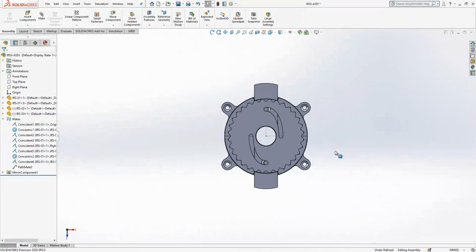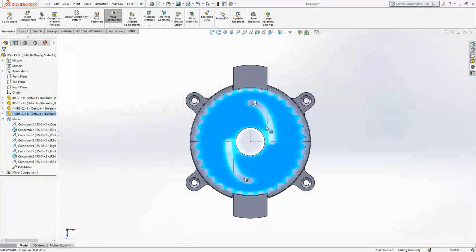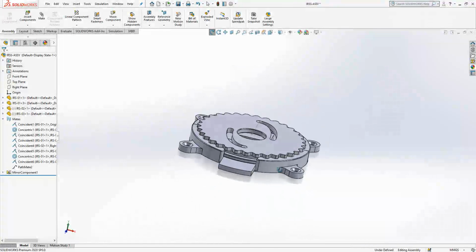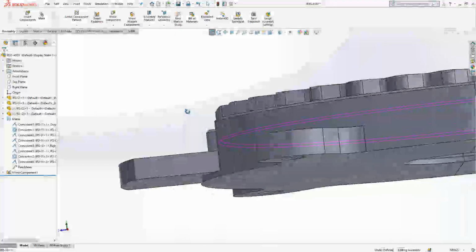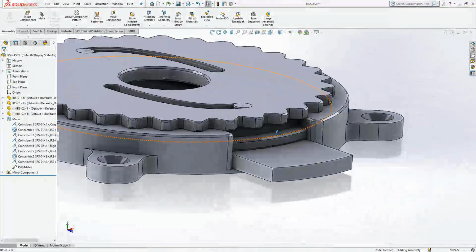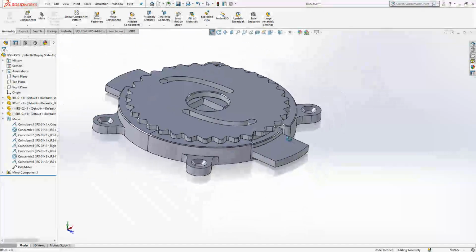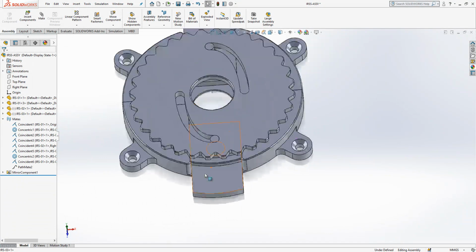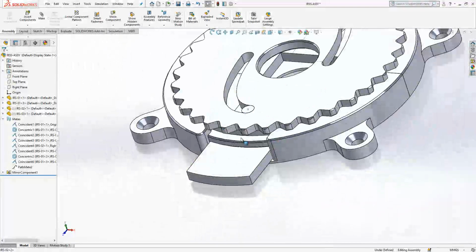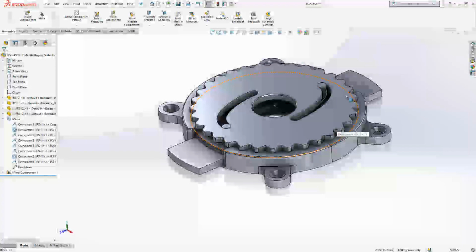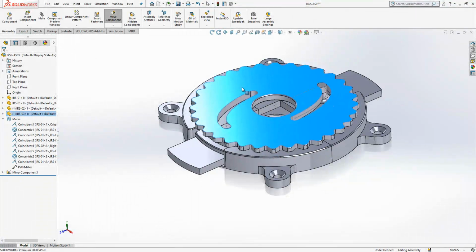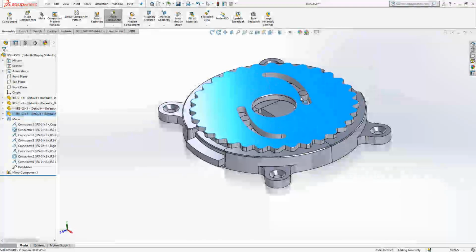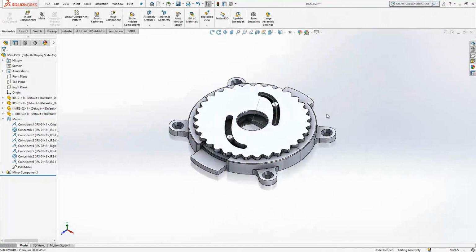Guys, this is it. With some little problems, we could complete our work. It looks fine, works good. One thing you need to take care of is that I do not have any tolerance gaps to let the system work. As you know, every system should have a certain amount of distance from each other to be able to work, not get stuck. For example, the thicknesses here. If you model this, do not forget to give some room for mechanical play. Otherwise, this mechanism will be stuck when you print it or produce it. So keep that in mind and enjoy it.